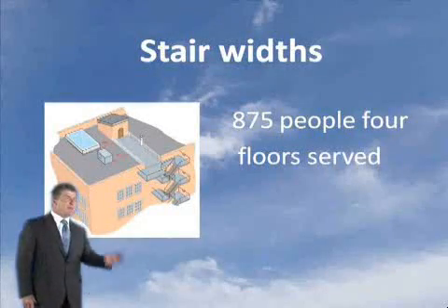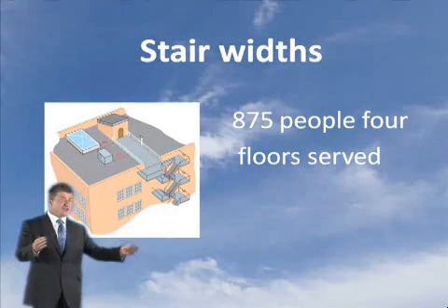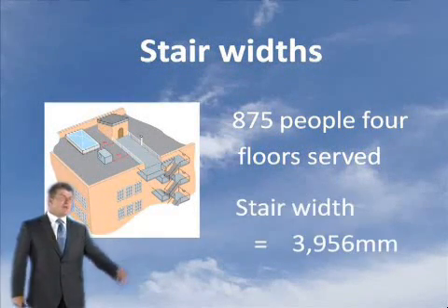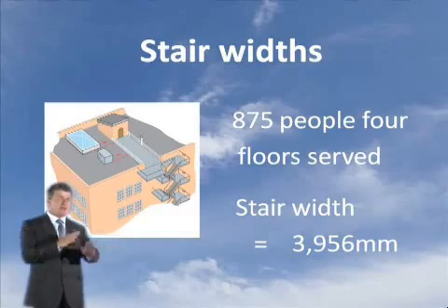Much better design. What about the stair widths then? This is just an example picked out. 875 people, 4 floors served. Very busy shop. Your stair widths are nearly 4 metres. Just standard 4 metres. That's without taking into account lobby approach. Have a guess what BS 9999 would say that staircase width would be with sprinklers.